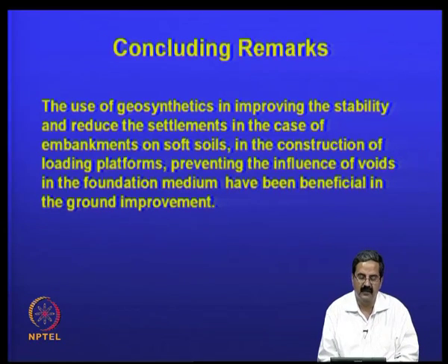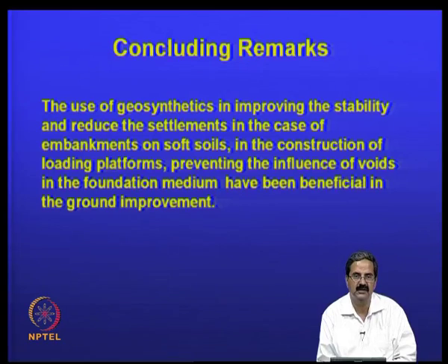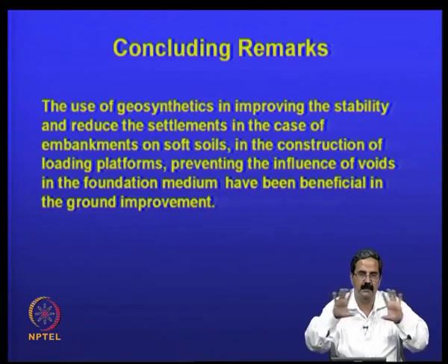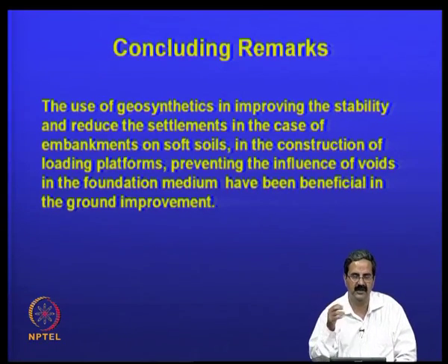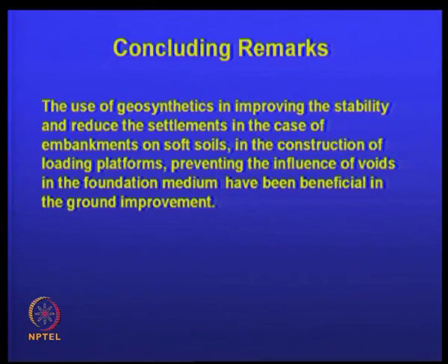So, there have been a lot of case studies on the use of geosynthetics in India, and the science is quite simple, as I also explained to you, particularly when you are trying to handle embankments on soft soils. You have to calculate the shear, and we have discussed internal stability and external stability. In the construction of loading platforms also you can use geocell foundations, and the influence of voids in the foundation medium can be avoided. This technique has been quite useful, because in many places in soft soils there is no other technique available, and people have perfected it in many places abroad and in India also.